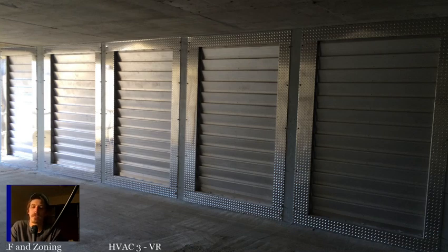It's not that difficult. Even if you have to pull some charge out to weigh it back in, if you've got even halfway decent recovery equipment, that is not a difficult task. The most important thing, the hardest thing to get out of that, is a good, clean, vacuumed-down recovery cylinder. As long as you have that, even the cheap recovery units these days usually do a decent enough job for you to pull most of the charge out so that you can weigh it back in.